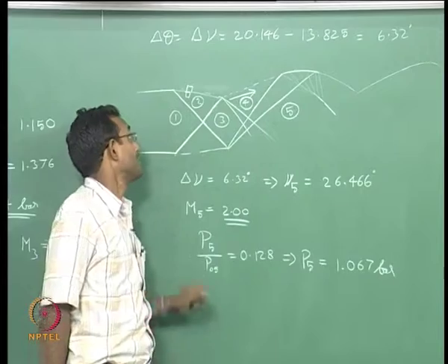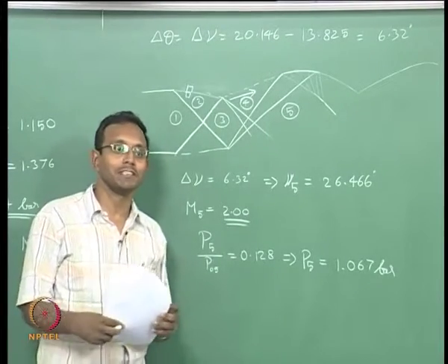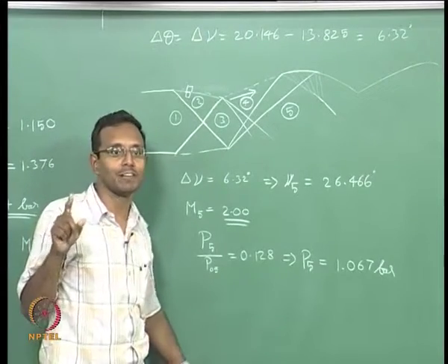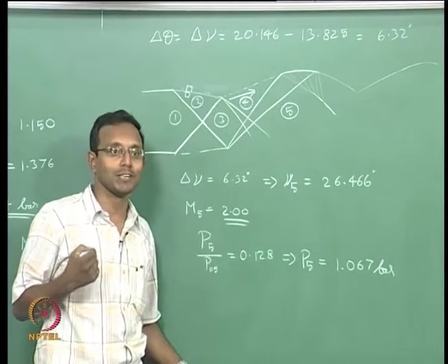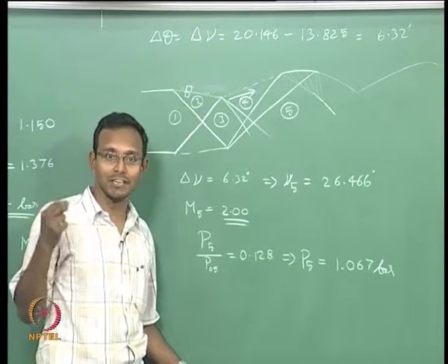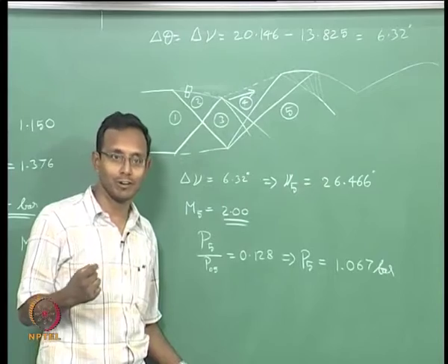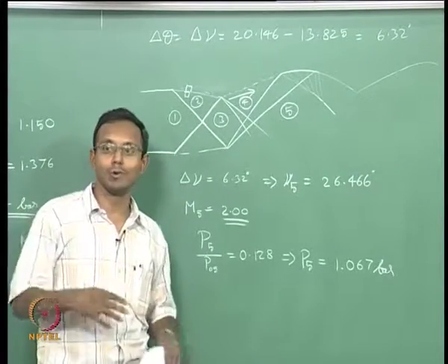If there is such a high velocity gradient at that point, you can immediately think about vorticity being present there. Vorticity is the curl of the velocity vector, del cross V. So immediately I can tell that there is non-zero vorticity present there. In real life, if there is concentrated vorticity present somewhere, the viscosity factor will come in and distribute this vorticity equally all over the place.